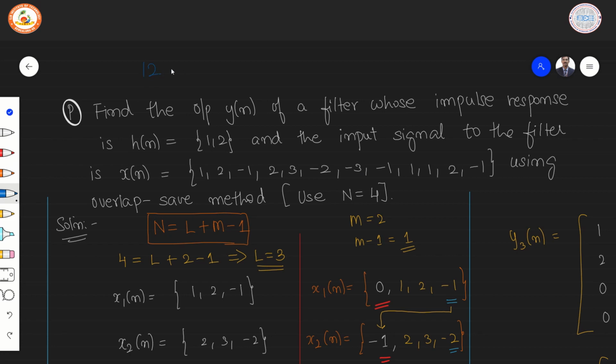The impulse response is of length 2. Therefore, since we are calculating the result for linear convolution, the answer is length of first sequence plus length of second sequence minus 1. We are expecting a total of 13 points as the output.